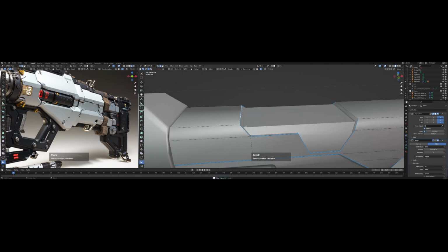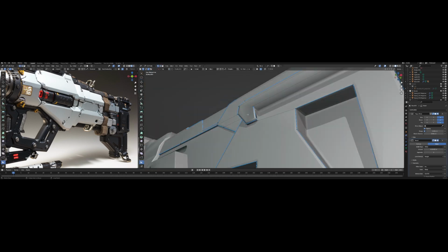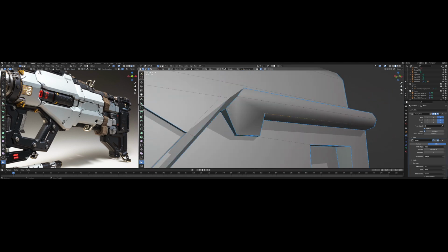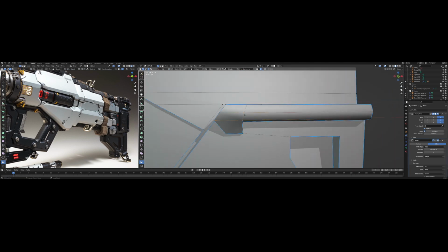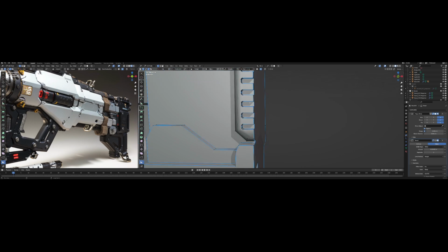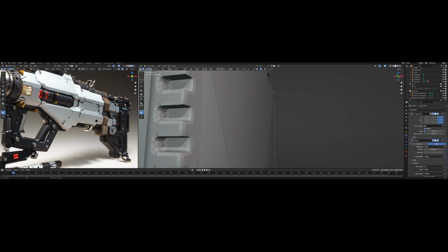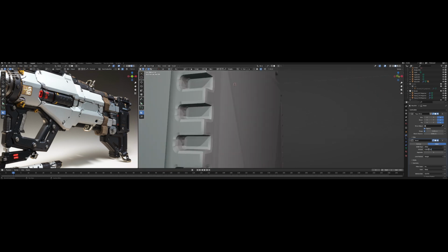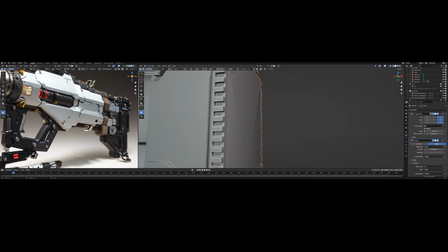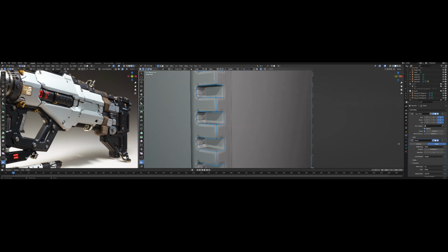So that's it. And another thing I want to mention: if we directly use the sharp by changing its degrees, it will help us solve most problems, but there will still be some missed edges that were not automatically marked, so we have to do it manually. As we can see from this part, the bevel weight that I have added on this one seems not smooth enough, so I will fix it later.